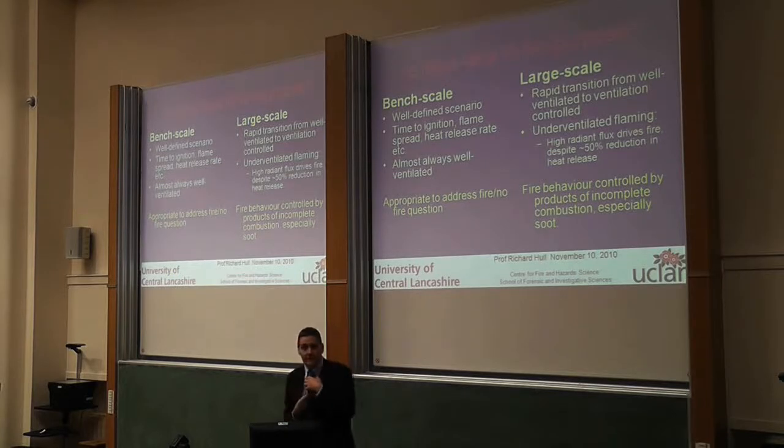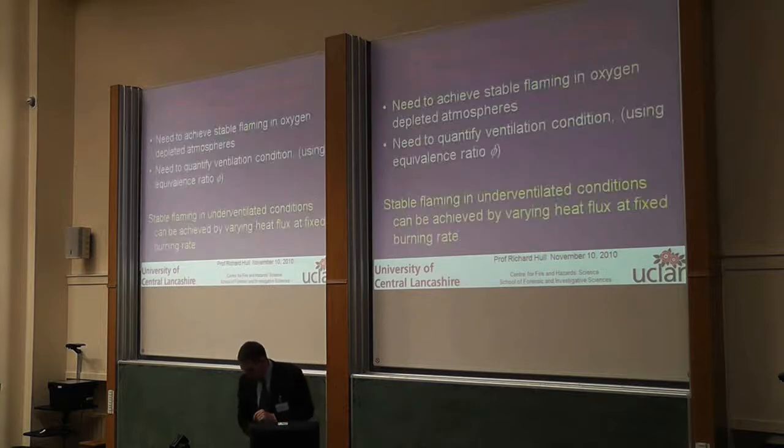The question that I'm asking this afternoon is whether you can also use that to improve the models that you have for fires when you're talking about your fire safety engineering assessments. Are you able to properly model underventilated flaming, or are you assuming the worst case scenario of well-ventilated flaming? This is why, in the wonderful work Guillermo published, the ability to predict the time to flashover shows a significant variation, should we say, certainly when you're using FDS.